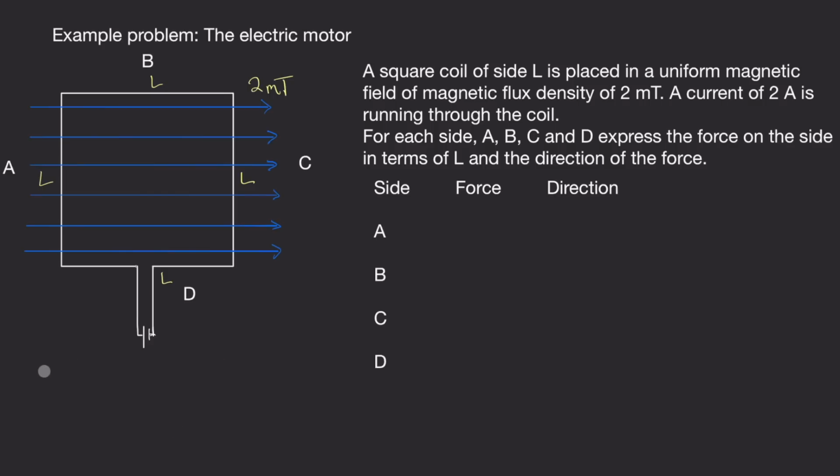So in this part of the circuit, we are actually given the terminals, and remember, the bigger one is the positive one and the smaller one is the negative one. You can just about see them over here. So this means that the current is going to go through here, through here, through here, and then back through there. If we know the directions for the current and the magnetic flux density, then we're in business. We can just use Fleming's left-hand rule to determine the direction of the force.